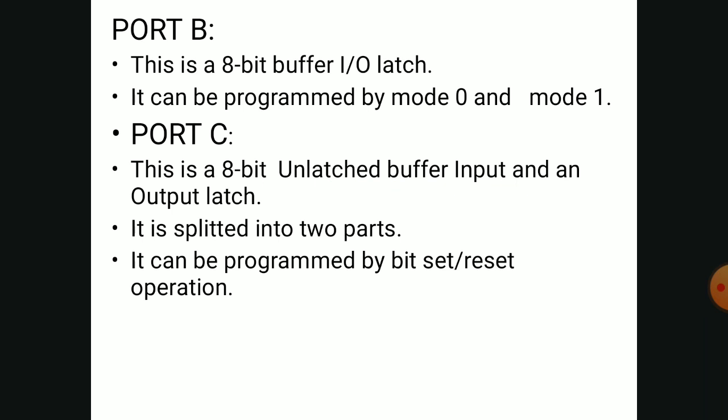Port C is also an 8-bit I/O latch. As I already said, it is split into two parts, port C upper and port C lower. It can be programmed in one mode of operation, which is the bit set or reset mode of operation. That also we will discuss soon.